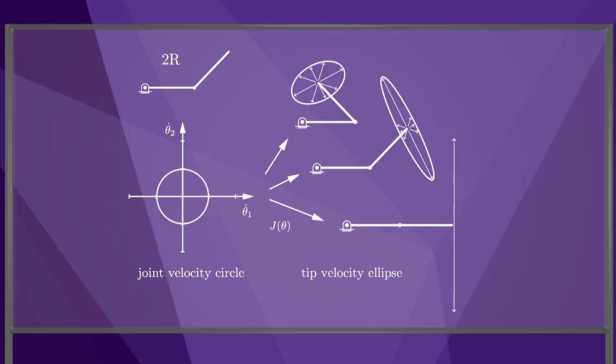As the second joint angle approaches 0, the ellipse squashes in the direction it is difficult to move and stretches in the orthogonal direction until, at the singularity, the ellipse collapses to a line segment. As we will see shortly, we can assign a measure of just how close the robot is to being singular according to how close the ellipse is to collapsing.